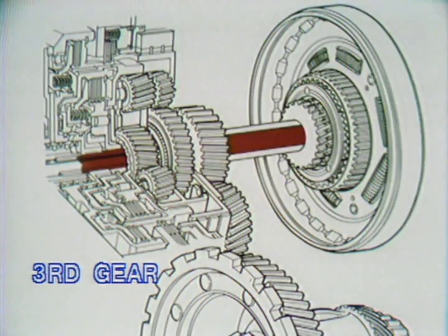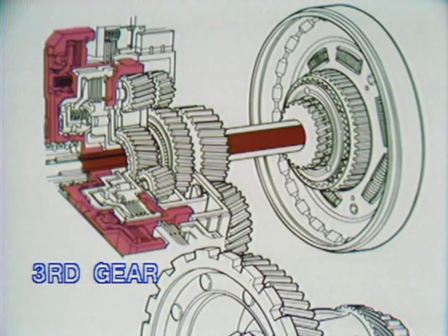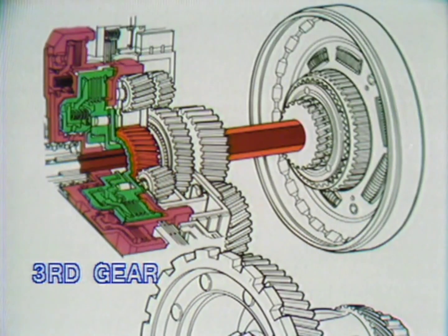There is a split torque input through the intermediate shaft and clutch to the main ring gear. With the direct clutch on, the low reverse sun gear is locked to the turbine shaft and thus to the converter. This causes the main gear train to effectively lock up, since 2 members are locked together through the converter. The planetary unit thus turns, in effect, at the same speed as the input shaft.